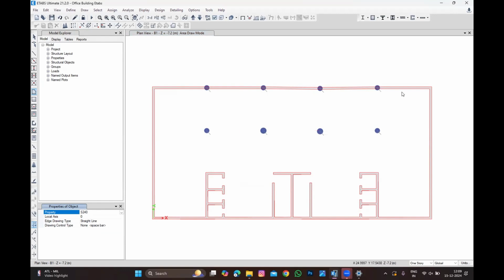Then start from here. First, can you look at my cursor? On the left side, there is a snap option, right? Always try to click the first and the fourth one. It's like the AutoCAD snap option. You don't need everything. First and fourth are more than enough.